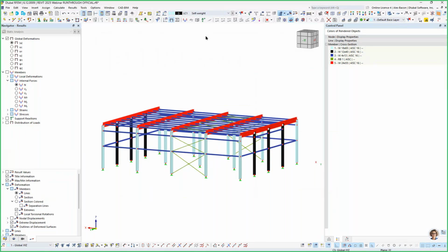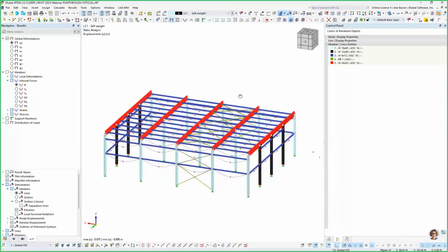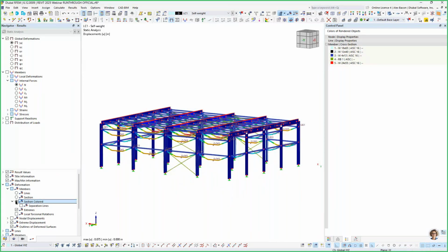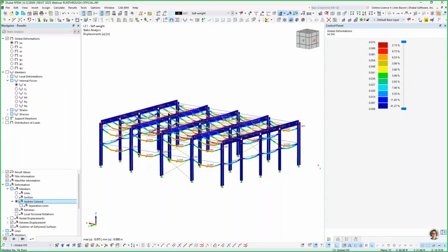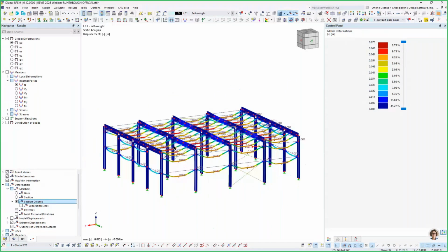And it's done. So now you can see the best thing to do really is to check the deformations. Deformations really tell you a lot about the structure. And right now ours are looking good. I can change this to colored section and a wireframe render. Right now we're getting a max of 0.07 inches, which is in our coupling members. So we can check the deformation.